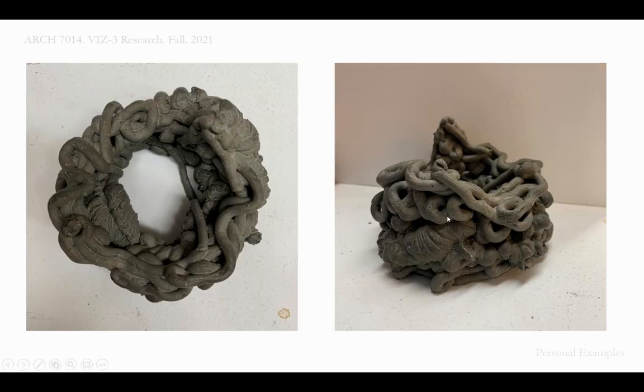And then again, this was just a simple cylinder, but this was a point where I didn't start at 0, 0. So when I began printing, it didn't start at the bed. It actually started half an inch above the bed, so that everything had a moment to fall before it actually made contact with the bed.